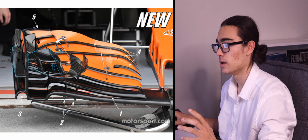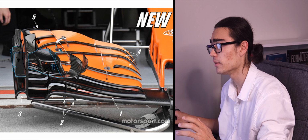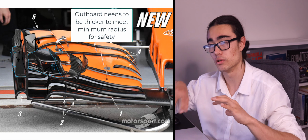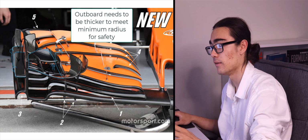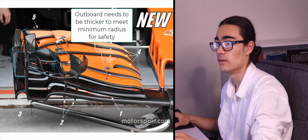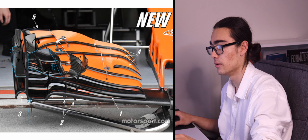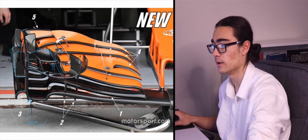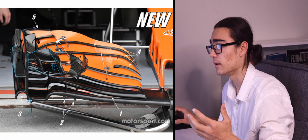One more thing while we're here, the turning vanes here, you can see they're very, very sharp. So these are shedding off quite a nice vortex themselves. You can really tune your loss with how sharp an edge is. You'll also notice that the McLaren here doesn't have it, but in the footplate region right there, sometimes they have a flat extension and they actually chamfer it up, so it's quite sharp on the end, and in some years they've actually curved it up like that. So you can directly affect your vortex creation like that.